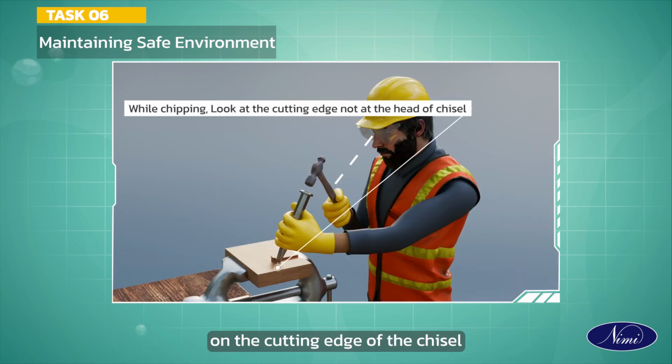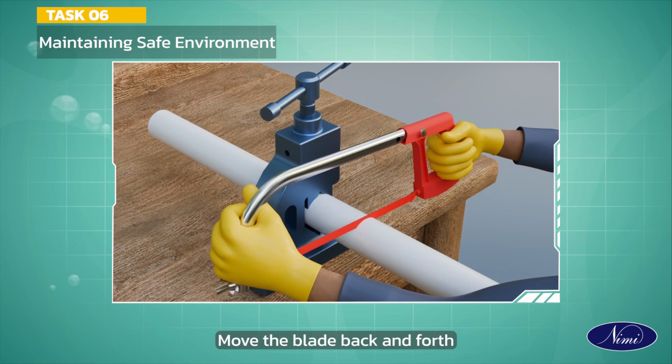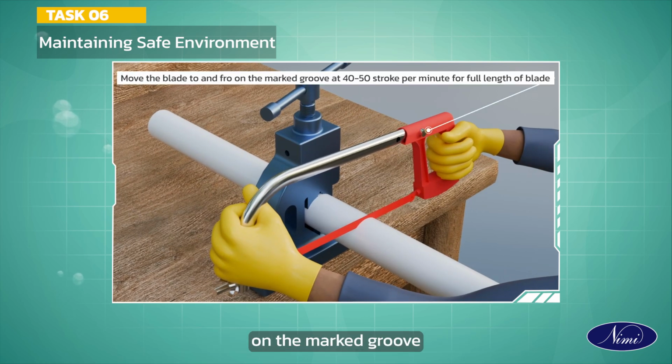Keeping your focus on the cutting edge of the chisel while working on a wood block is crucial for precision and safety. Move the blade back and forth on the marked groove at a speed of 40 to 50 strokes per minute for the full length of the blade.